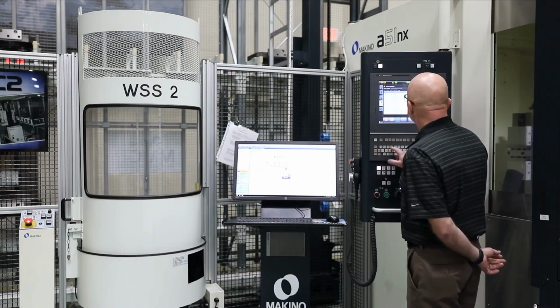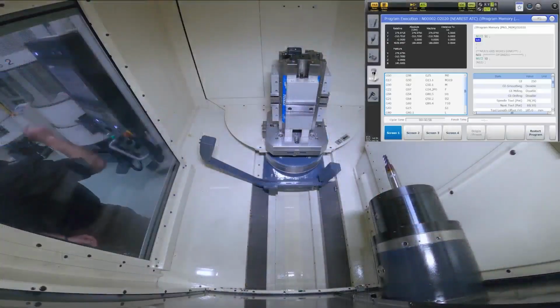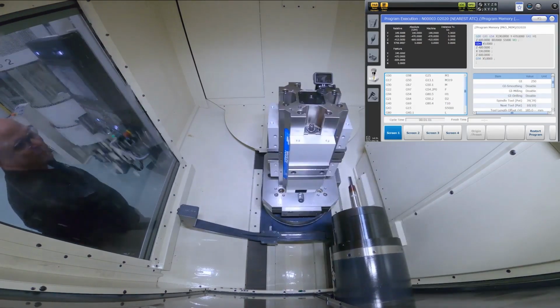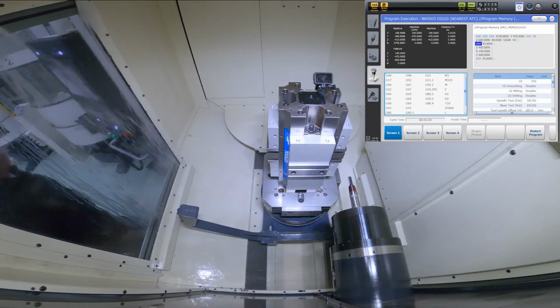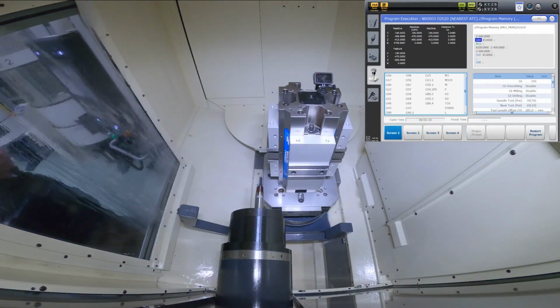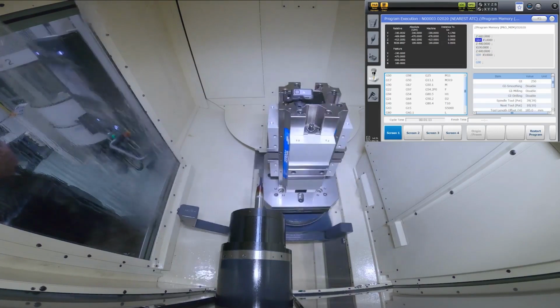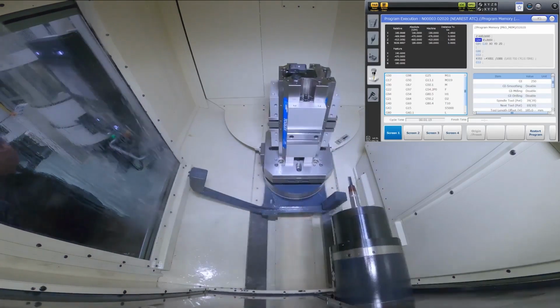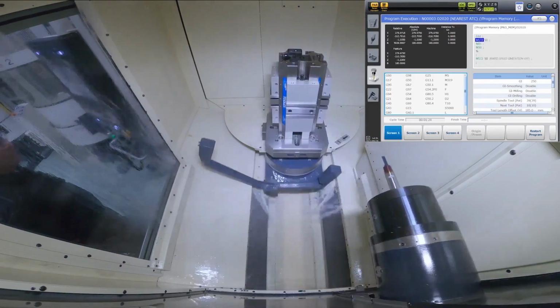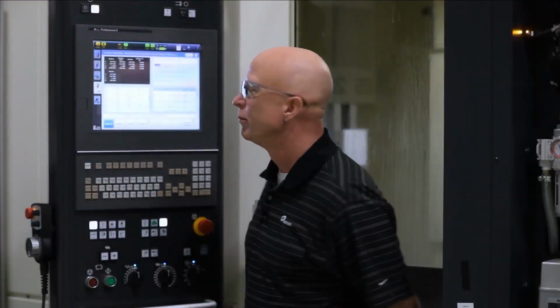So let's move back to our program. And let's run this last demonstration. Last demonstration is the optimized motion, including multi-axis moves. Oh, look at that. All 4 axes moving at the same time. And this is where I said you have to be careful with this optimizing. Watch this one. Same thing here. When it rotates, multi-axis positioning. And then end, of course, with the position next to the ATC. And this does require the FANUC parameter change.